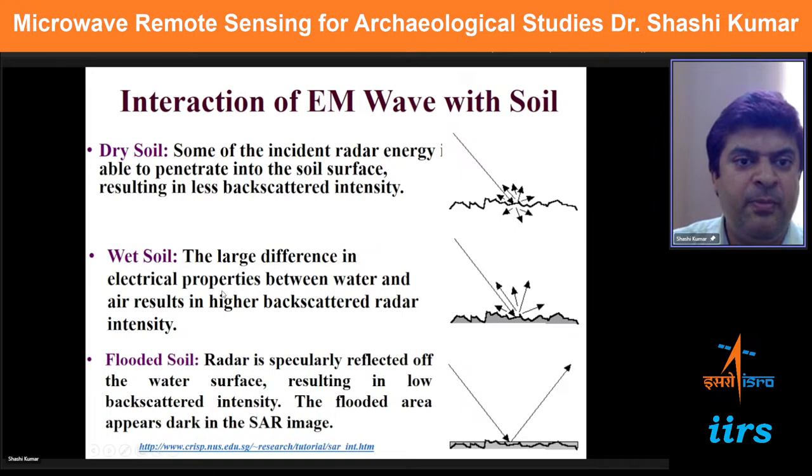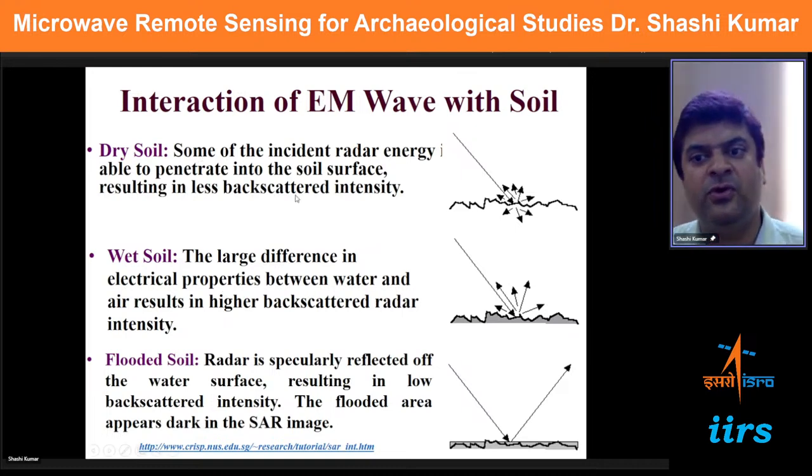So here we will have to keep in mind, when we talk about subsurface information retrieval or buried object information retrieval, that we will have to select those days or that season in which the soil is dry. Then only can we get some subsurface feature information.